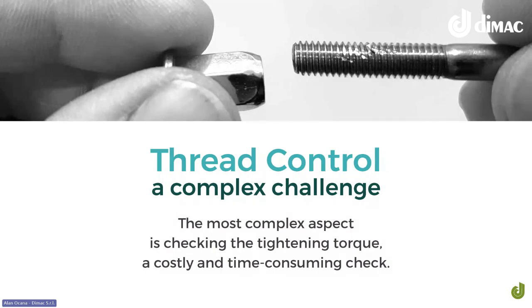And it's not just because of the geometry. Yes, we can measure things like overall length, inner and outer diameter, crest height, and crest count. Those are relatively straightforward. But what really matters to the end user is how well the thread engages, its ability to hold under load. And that depends on tightening torque.